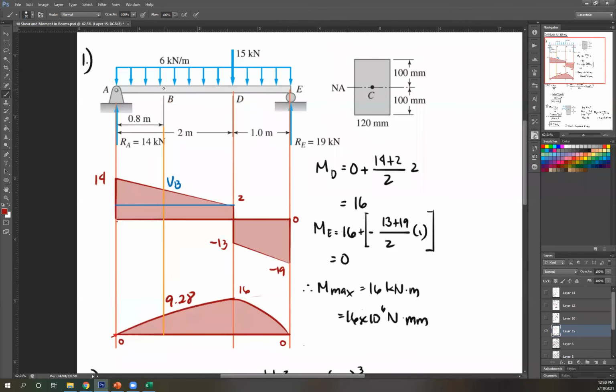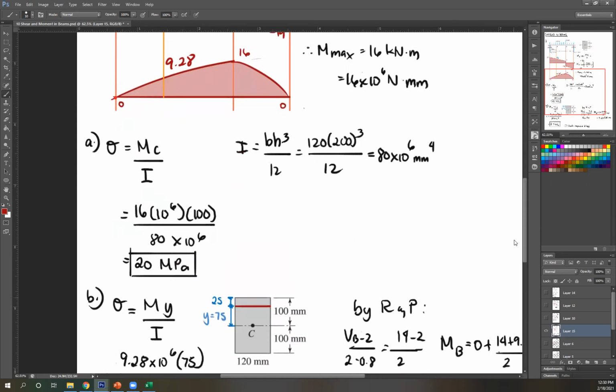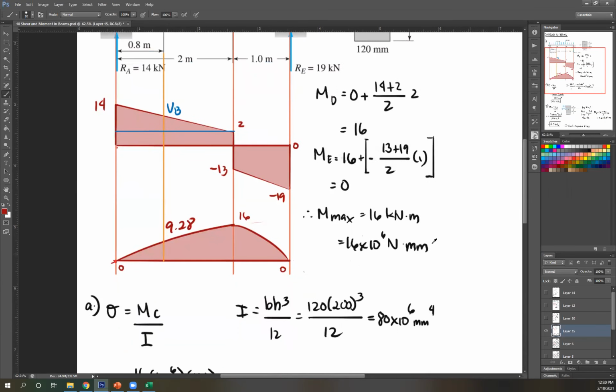So again, I want to know flexural stress there. And the equation is My over I. Okay, not C anymore, since that's for maximum. So I need to know M. So therefore, in my shear moment diagram, I need to know this point. Okay, so how? To get that point, that's the first thing we need to do. That is the area of this. To get the area of this, which is another trapezoid, I just need the height of this. So let's call that VD.